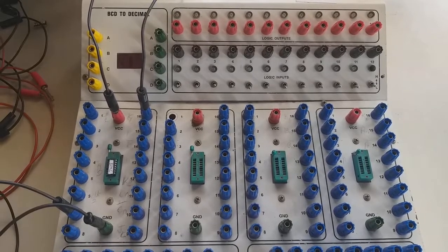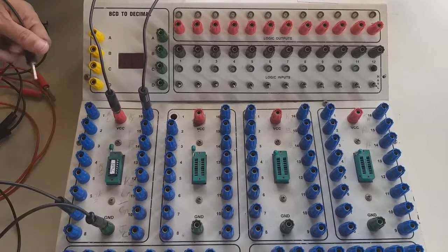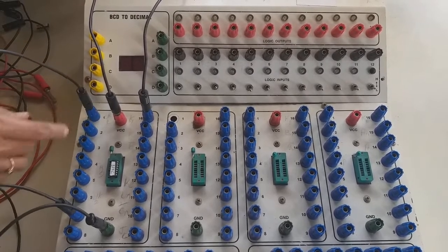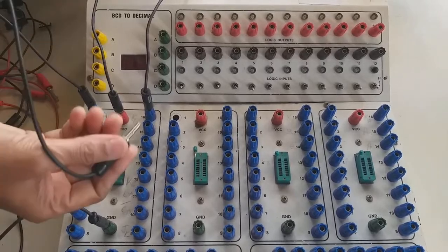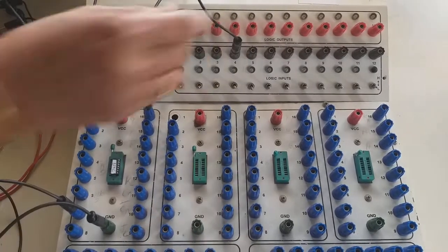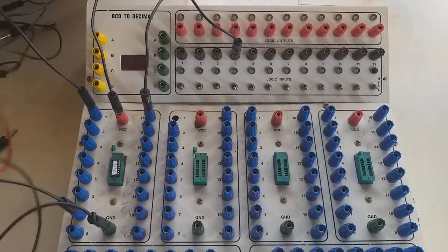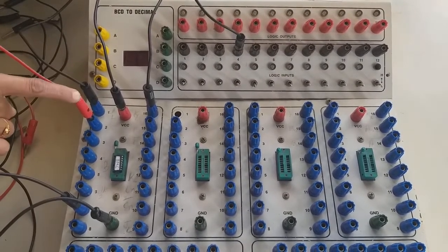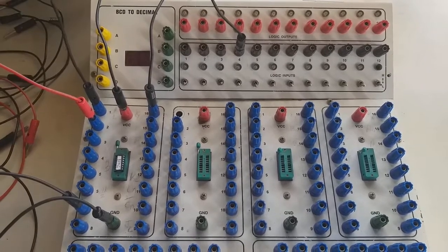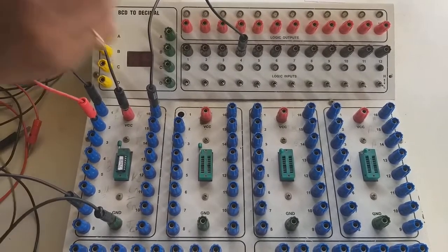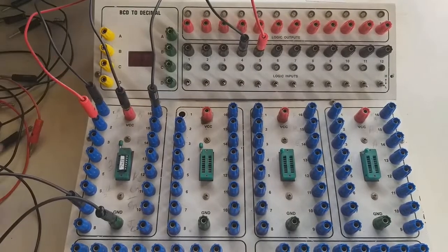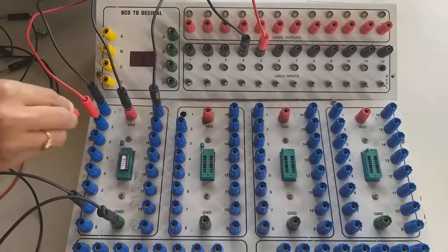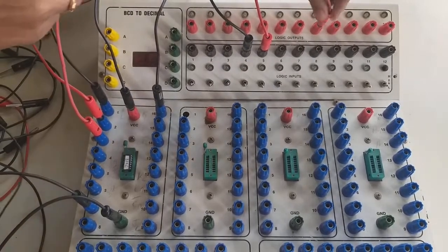Okay. So with respect to the working principle of the AND gate, it has 2 inputs and 1 output. So the 2 inputs are pin number 1 and pin number 2. So one input I will take for pin number 1, connect it to one of the input slots. Then the second input is another input, that is B. A is black, B is red, I have taken. So A I have connected to the input line, B I will connect to one more input line. Okay. 3 is the output, so connect it to the output pin.